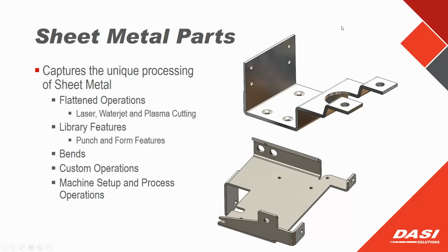Last but certainly not least, I wanted to circle back and talk a little bit more about a sheet metal component and how we approach each of those. Sheet metal parts are those parts that really have kind of a dual life. They work in a flat pattern. A lot of geometries are then lasered out in that flat pattern, and then the part goes through the forming or folding process to go to its 3D life.